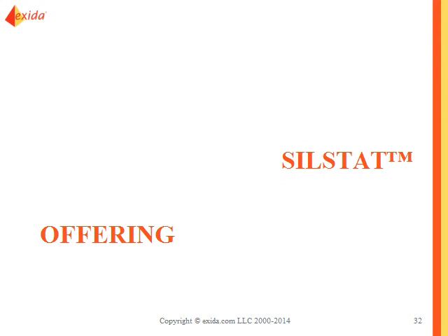Now, the focus in exSILentia is on specifying what the different steps are. You can update that in SILStat, but the focus should really be in the conceptual design. You've assumed a certain proof test coverage. You may talk about a certain proof test coverage on a valve, and the higher the proof test coverage you claim, the more extensive your test needs to be. That's something that you want to document up front there during your conceptual design.